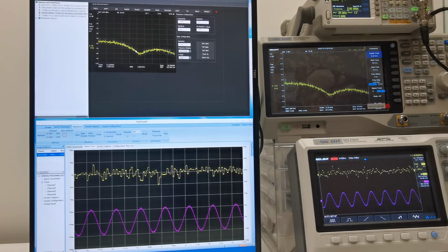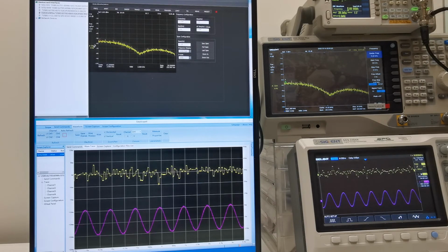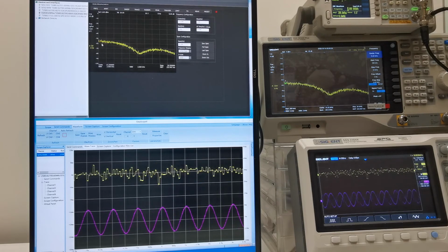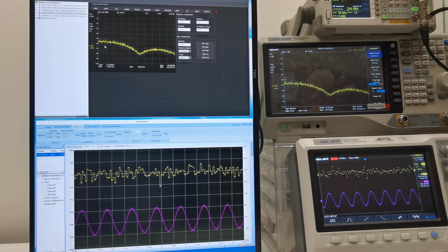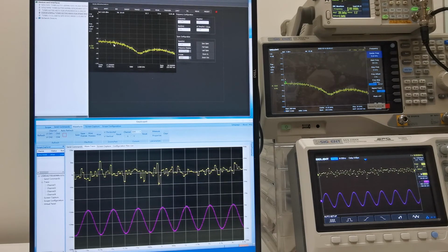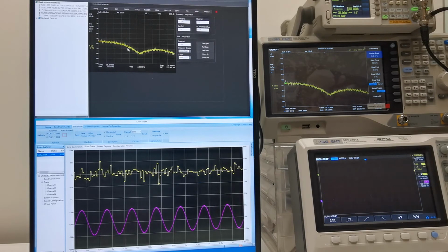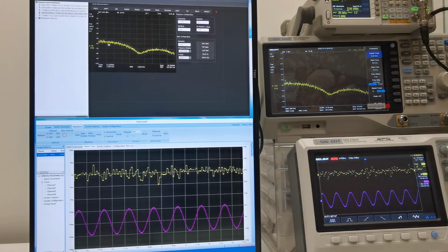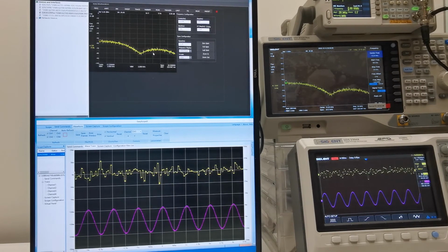And on the front panel, we can easily set the frequency range to a wider span, so we can get a better look at the full span. We can see it's not a perfect white noise because the spectrum is not really flat, but it's good enough for most applications. Now we have tested a sine wave, a square wave, and noise, and we are going to do more tests on some more complex signals, like modulated signals.